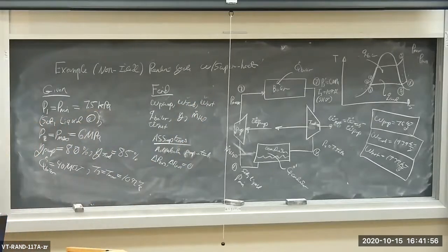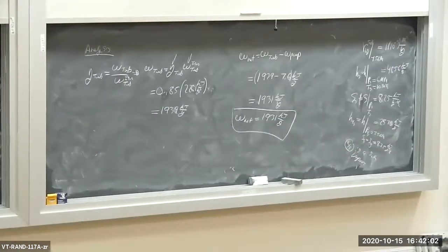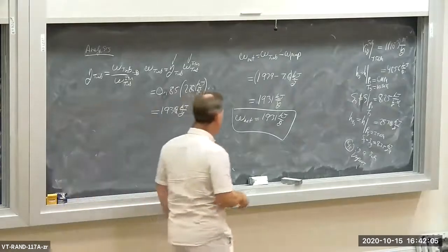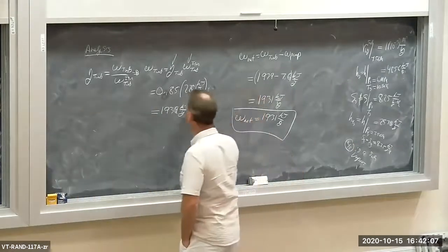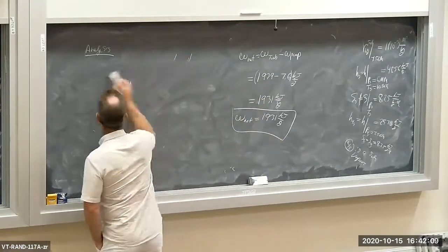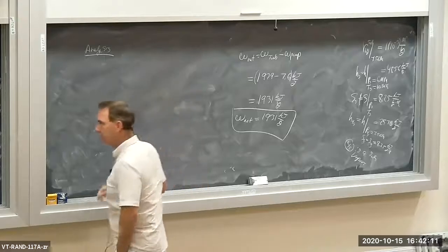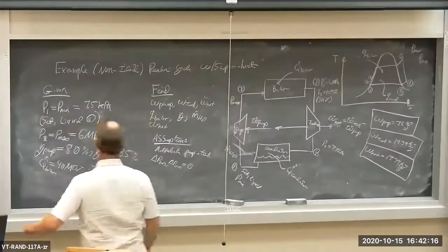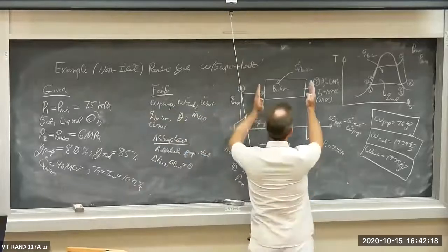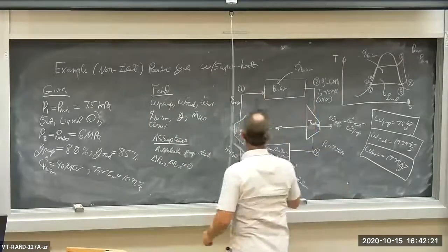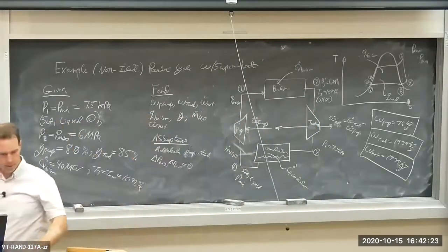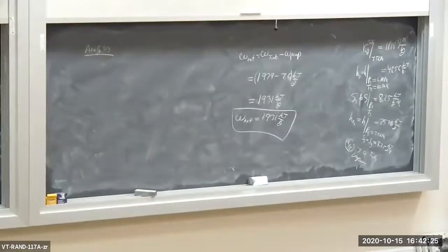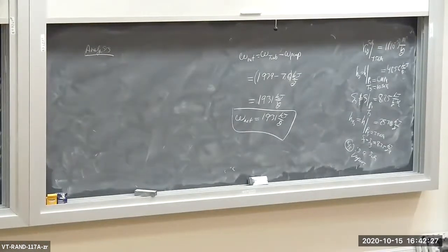Let's find the heat addition to the boiler, Q to the boiler, that's per unit mass. Application of the energy balance over what process? From the boiler inlet to the outlet, so from state 2 to state 3. There's no work interaction going on.